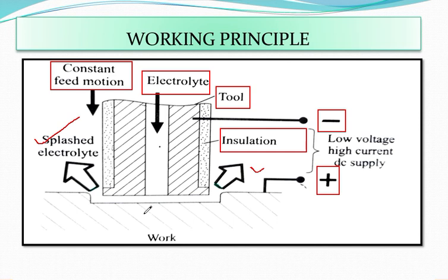And you can see the electrolyte is pumped at a high pressure through the tool and the gap between the tool and the workpiece. The electrolyte is so chosen that the anode is dissolved, but no deposition takes place on the cathode, I mean to say on the tool.